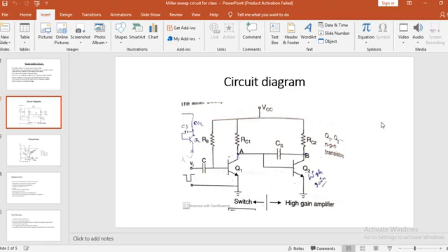It increases very gradually. Now, when the voltage at point A, that is Va, is increasing gradually, the voltage across the capacitor starts falling gradually. With Q1 off and the potential of point A increasing, Q2 becomes on.